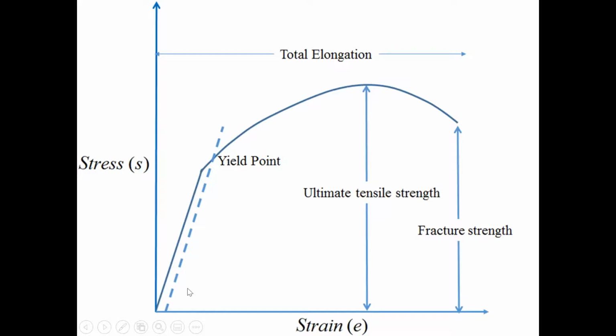So if you have a metal and you start stretching it, then the first thing that's going to happen is you're going to go through the elastic part. This is where the Young's modulus is relevant. So if you pull the sample, in other words, Hooke's law is valid. If you stretch the sample, the stress-strain relationship is linear. And the slope of this is the Young's modulus. And if we take away the stress, it'll go back to the original position and there won't be any plastic deformation or permanent set. In other words, we haven't destroyed the sample.